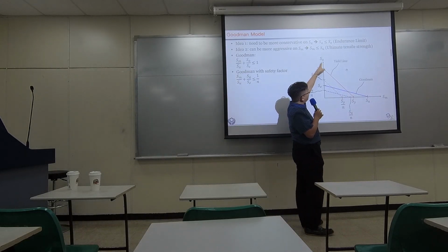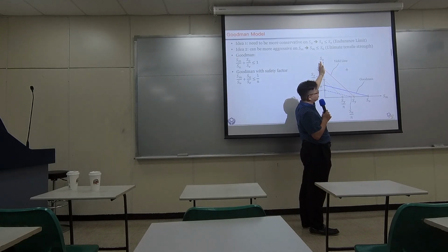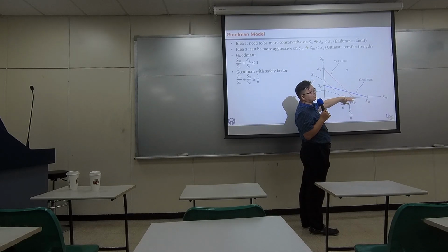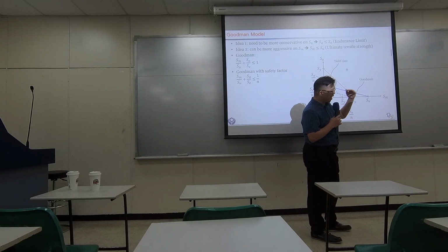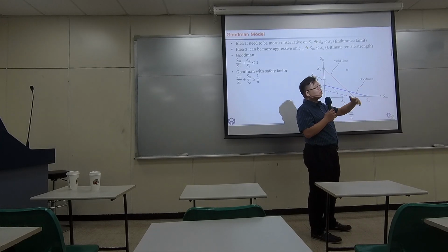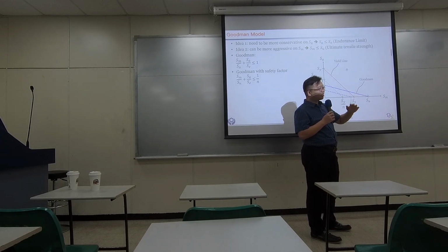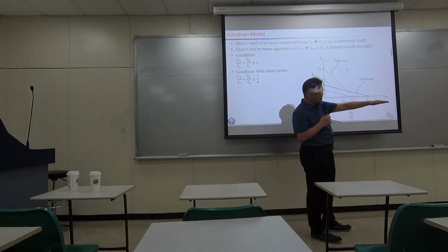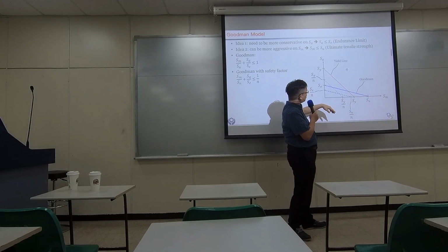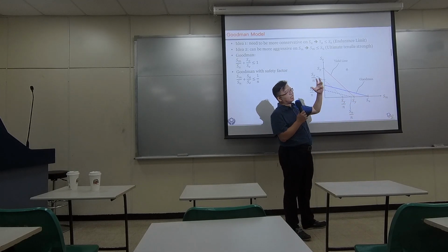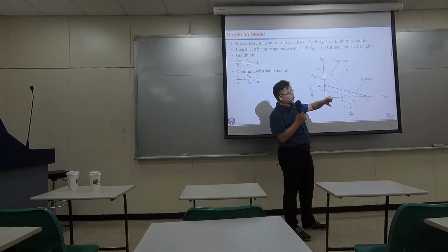the amplitude of the stress is representing the dynamic part of the stress, not the mean one. Because the mean stress, if we are applying exact same stress over the time, it's just that we have cycles. If that stress is always looking like that with a certain mean and certain amplitude, then the mean doesn't change with time. So what is making the material strength reduce is actually the amplitude.